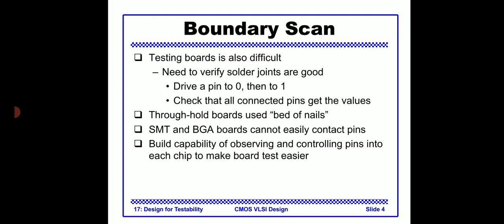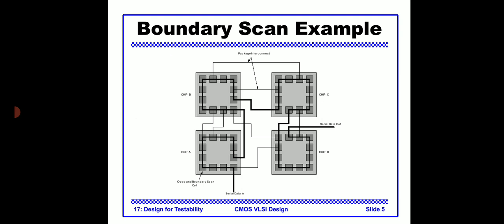Boundary scan adds one or more test cells connected to each pin, and it can selectively override the functionality of each pin. These pins, arranged in chains, are driven to a signal across the board. There will be a programmed board that reads the value of the pin and verifies that the board is properly connected between these two pins.